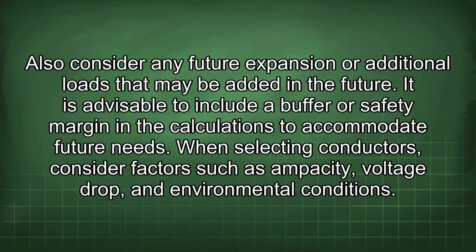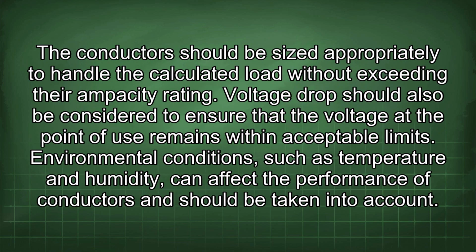When selecting conductors, consider factors such as ampacity, voltage drop, and environmental conditions. The conductors should be sized appropriately to handle the calculated load without exceeding their ampacity rating. Voltage drop should also be considered to ensure that the voltage at the point of use remains within acceptable limits. Environmental conditions, such as temperature and humidity, can affect the performance of conductors and should be taken into account.